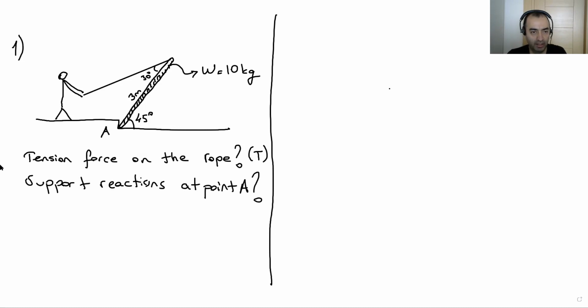So if this is a balanced position, we can find the tension force on the rope, and we can calculate the reaction from the ground, because here there is a step, this member stuck to this point, so it gives down a vertical support, vertical load, and also it gives a lateral load. Depending on the force and reaction principle, the ground, this part, gives our structure reaction forces.